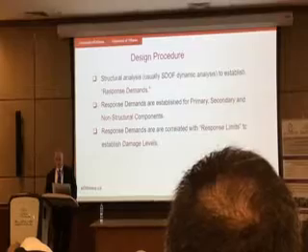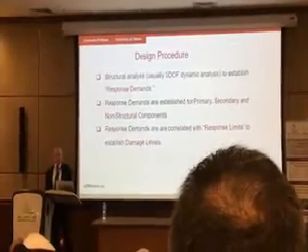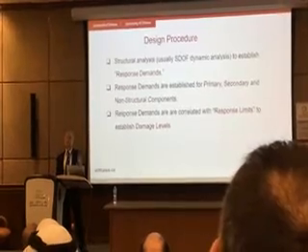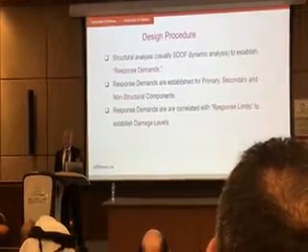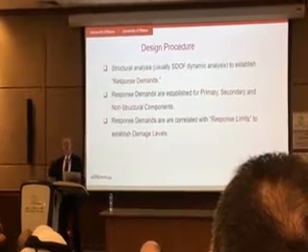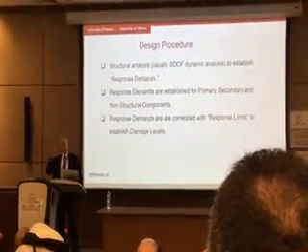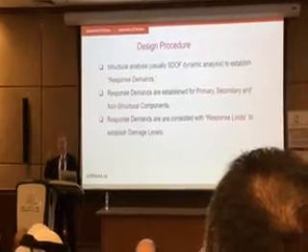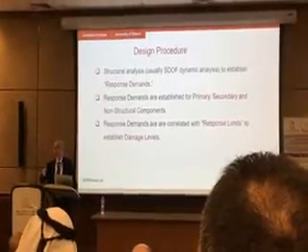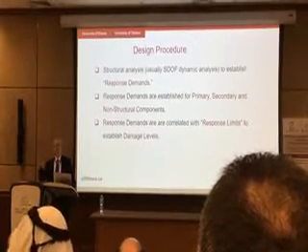Okay? So we do in the design procedure single degree of freedom analysis to calculate response demands. When you do single degree of freedom analysis, if you do nonlinear analysis, there are similar charts for nonlinear analysis. It tells you how much moment is imposed on the element, how much displacement is imposed.